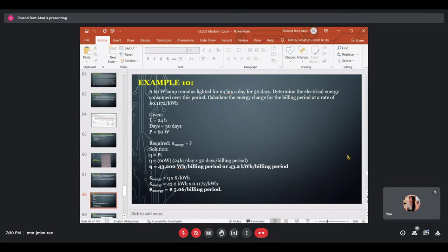In terms of commercial buildings and industrial settings, our energy consumption is present minus previous, then multiplied by the multiplier. Because the multiplier for industrial or commercial is a large value. Let's say 40, 80, 100, 150, and so on. So it actually depends on the current transformer attached to the system.